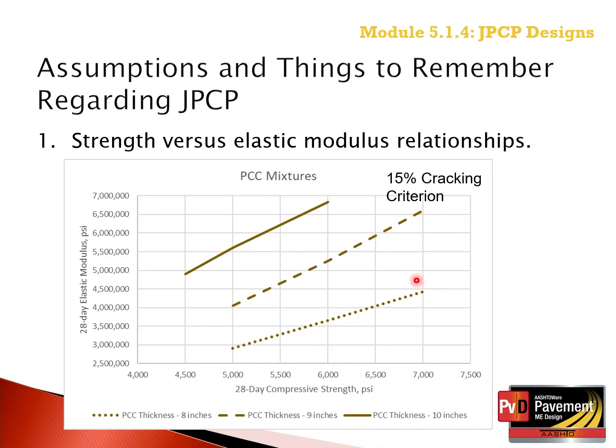Now remember, the software uses the flexural strength in calculating fatigue damage, but as a user, you can enter the compressive strength. The software converts the compressive strength to a flexural strength. The relationship included in the software between 28-day compressive strength and 28-day flexural strength was presented in Module 4.4.4 on the concrete material property inputs.